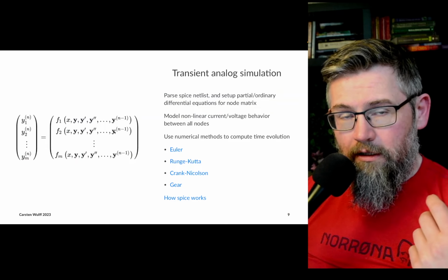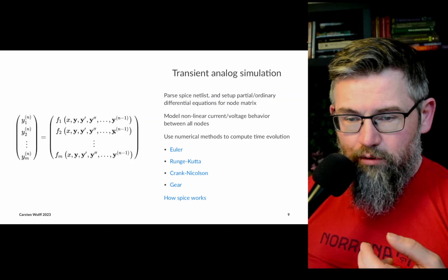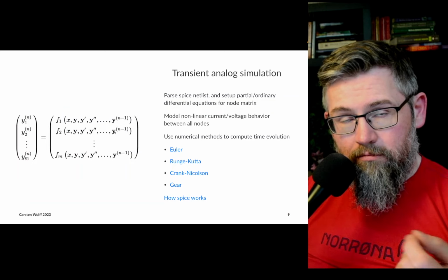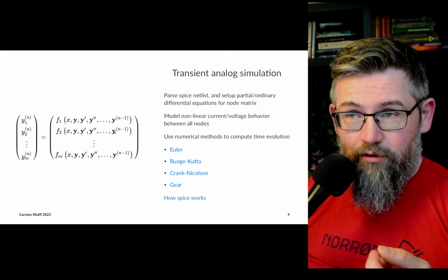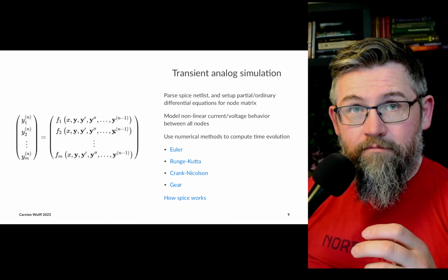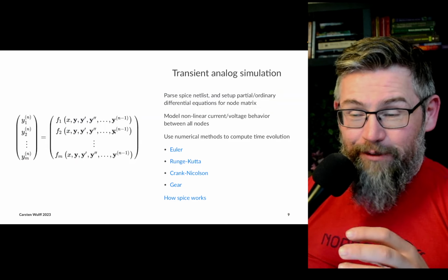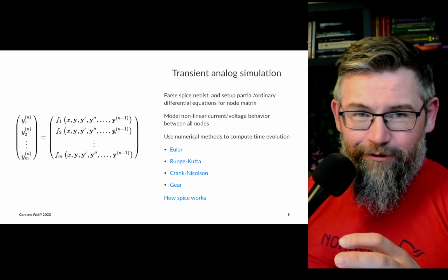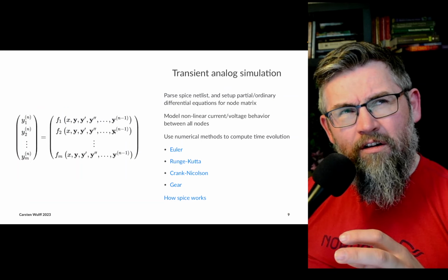to be able to compute the derivatives and the current states and the integrals, and just a simple thing as computing the current that goes into a capacitor. So we know that I equals C times dV, so derivative of voltage divided by time. Or, yeah, I equals C dV/dt. So in that case, we actually have to integrate the voltage change times the capacitance to find the current. Was that correct? Yes, it was.